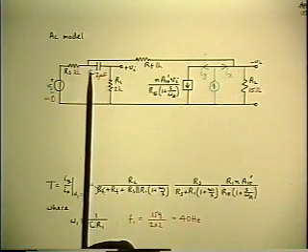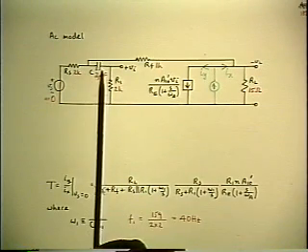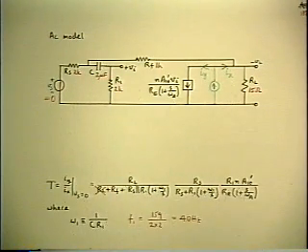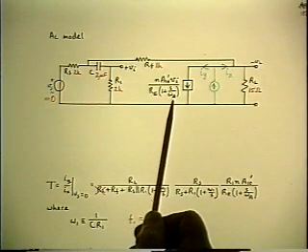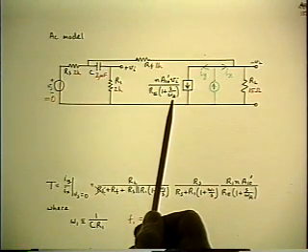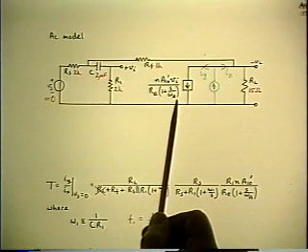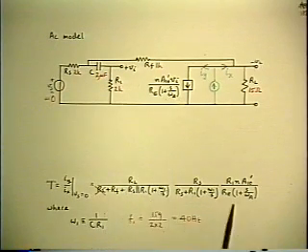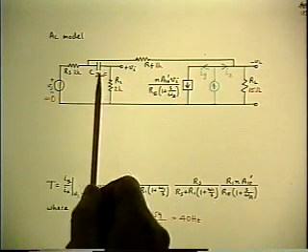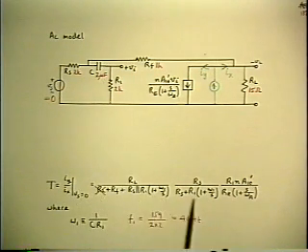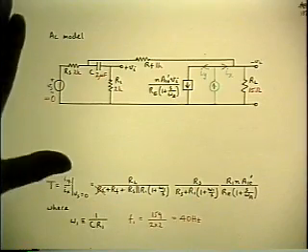So replace it with a short and find the mid-band value of the loop gain that results and call it Tm. At the same time, you can drop the explicit pole, omega A, which is part of the op-amp specification. So the mid-band value of loop gain is obtained by dropping the omega A and dropping the capacitor, which means dropping the other S terms as well.